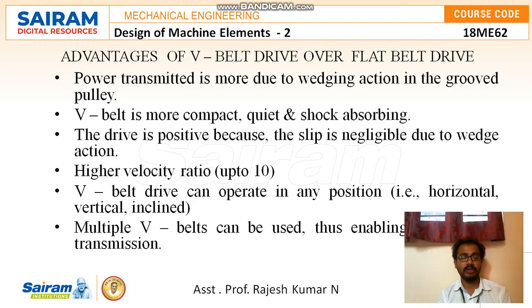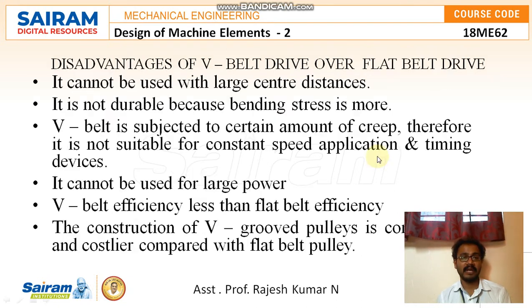Here the velocity ratio value is considerably good, and V belt drives can operate in any position, that is horizontal, vertical, inclined, any position is possible. And we have multiple V belts that we can use, and that enables more power transmission.